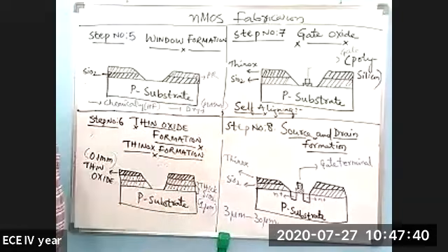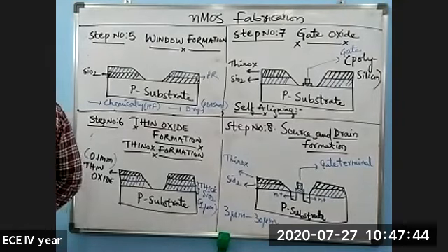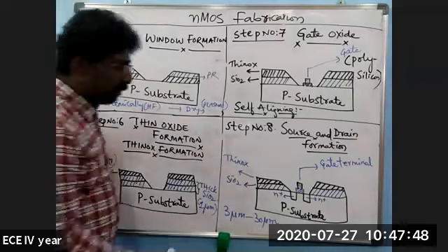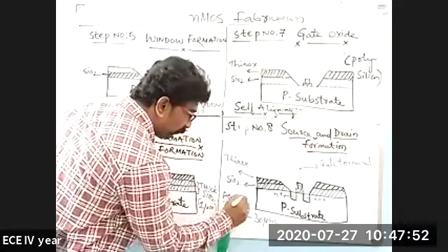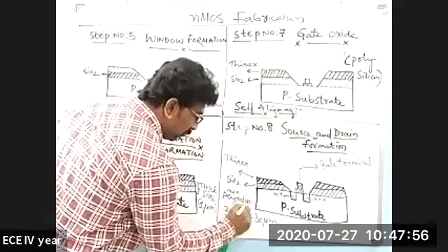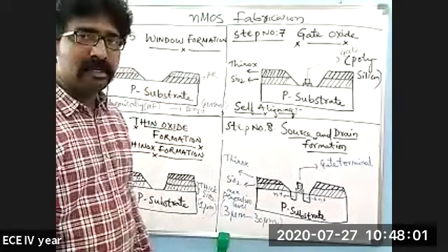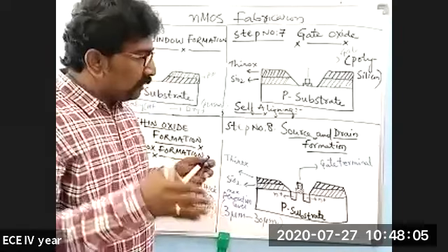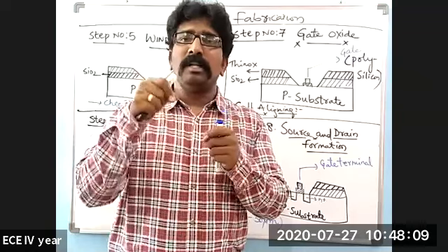So now the maximum penetration of these impurities will happen from 3 micrometer to 30 micrometer. This is the penetration. The maximum penetration level happens from 3 micrometer to 30 micrometer in this particular substrate, and the speed at which these impurities are being diffused into the substrate.